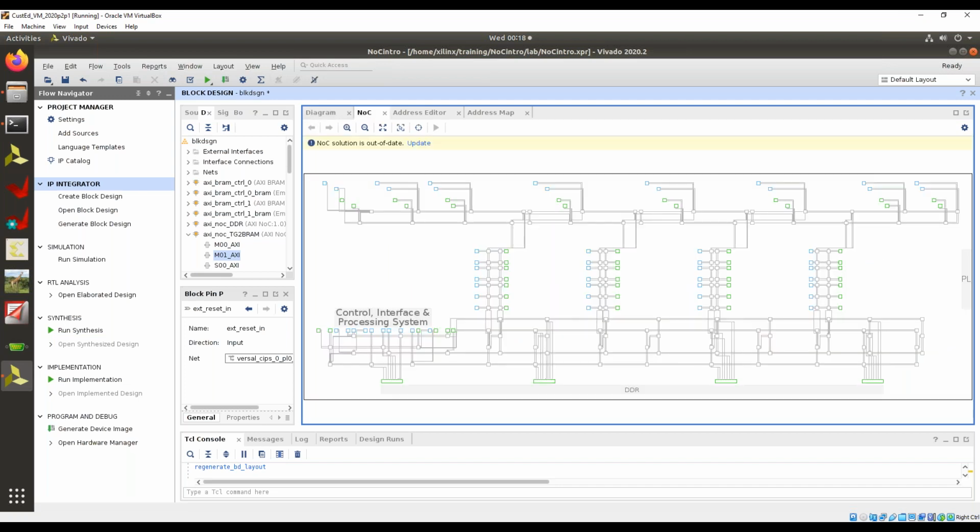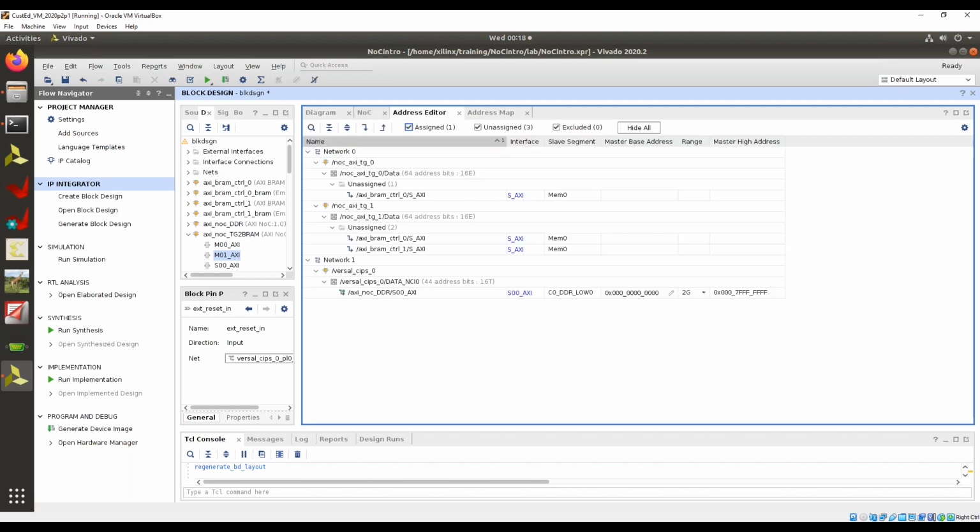We look at our NoC and look inside the NoC and go, okay, there's our basic NoC again. You can see, and you'll see in a few minutes, nothing is actually connected at this point. And that's okay. We haven't tried to validate the design. Once you validate the design, you're also trying to compile the NoC, which we've not tried to accomplish because we've not quite finished everything yet. So we go into our address editor again, which is available here, and we look at this and say, okay, our DDR4, those addresses are very well known, but what do you want to do with these as a designer?